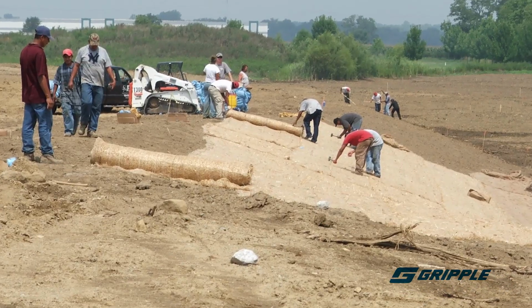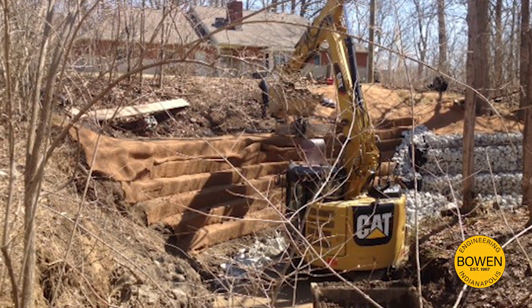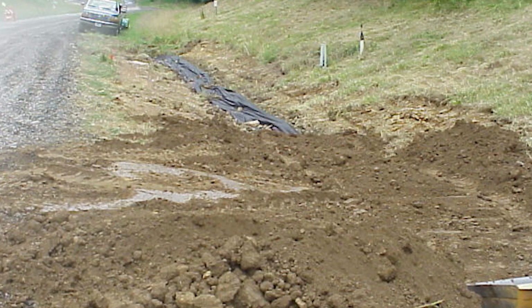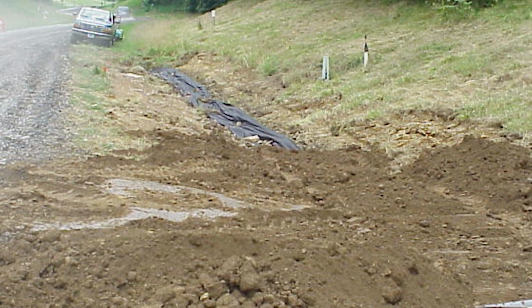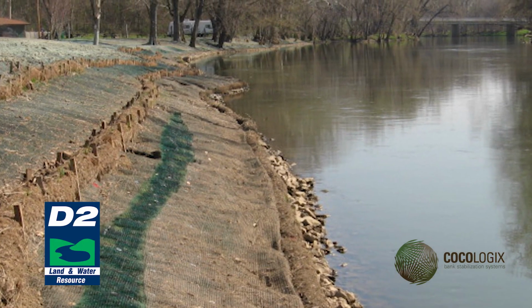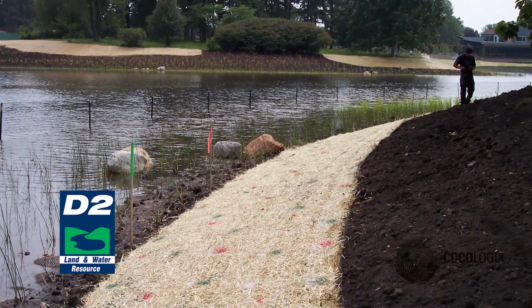The chosen RECP should be applied up and down the slope, never along the contour, and as shown in the construction plans. Blankets and mats must be anchored. How to maintain. Pull back the portion of the blanket covering eroded areas, add soil and tamp, reseed the area, replace and staple the blanket. How to inspect. Inspectors should check for erosion or displacement of the blanket.